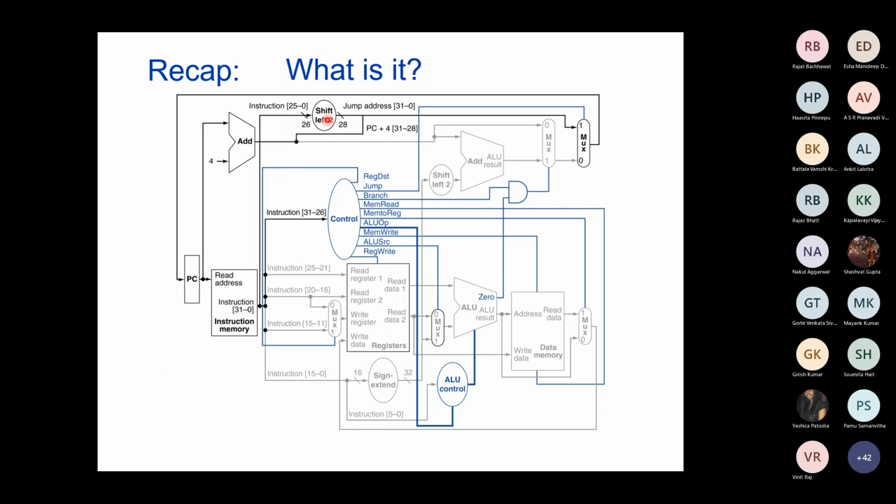So you can see here, this is the portion where the jump instruction has been taken care of to find out the target address, and this is the logic that takes care of the branch address whenever the branch is taken, and you have all these AND gates and so on, all kinds of data path. This is the primitive processor or data path, you can say, for implementing these basic instructions: load, store, add, subtract, and, or. And you remember that this ALU also realizes the SLT, set less than instruction, branch equal, and jump.